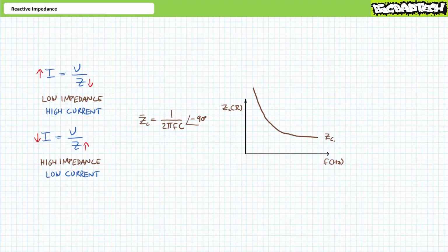This makes sense. Above DC or 0 Hz, slowly oscillating waveforms present slowly changing voltage. As a result, the charge or discharge process doesn't have an incentive for a massive exchange of current, i.e. current is low at low frequencies, synonymous with a high impedance element. This lack of incentive to charge or discharge results in sluggish, low magnitude exchanges of current.